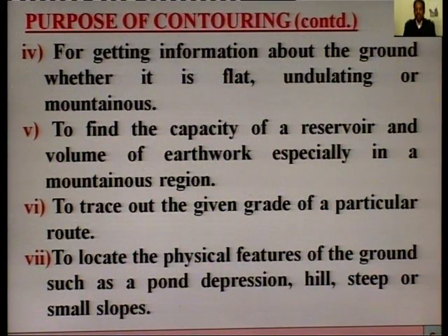The next is to find the capacity of a reservoir, that is, how much water it can store, and the volume of earthwork, how much earthwork is involved, especially in a mountainous region. Generally in a hilly area, we have to know the capacity of the reservoir in which water is to be stored, or how much earthwork is involved, whether in cutting or in filling. So, for doing such things, we do contouring.